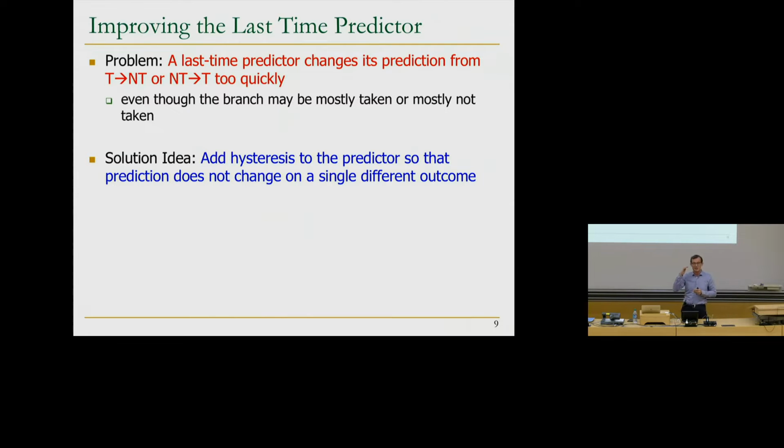Why? Because let's assume that you're exactly at 22 degrees Celsius at that point, and you're cooling the system. Once you start cooling, it'll go down to, I don't know, 21.999 degrees Celsius, right? If at that point the heating system kicks in and starts heating the room, then you go into heating mode, and the temperature increases and you get to 22.0001 degrees Celsius. At that point, the cooling system kicks in, and you go back to a temperature lower than 22 degrees. At that point, the heating system kicks in. So you have a problem of oscillating, right? There's a problem of oscillation if you change your mind too quickly after you make a decision.